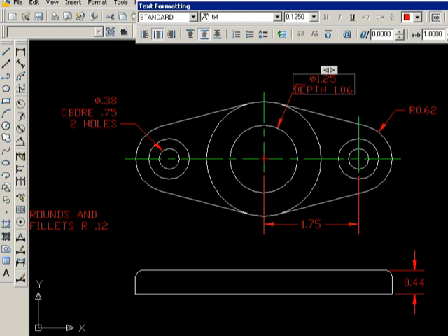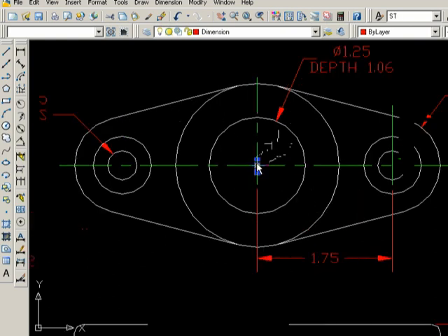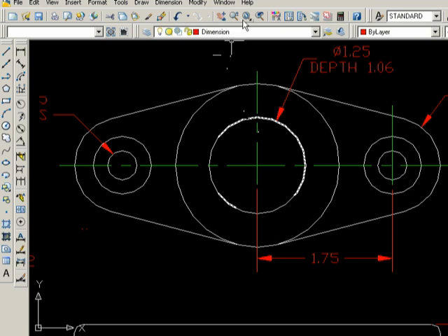All right, click OK. I've just got 2 problems I got to clean up. Notice you're never, ever supposed to overlap lines in text. And notice my depth term is overlapping my leader line here. No problem, just highlight, click once, grab this blue handle, and drag it over to the right. All right, and that cleans that up. Last but not least, again, I got to zoom in, and I got to get rid of these red lines. I click those, I click delete. Red lines do not overlap center lines. All right, I click the all button,